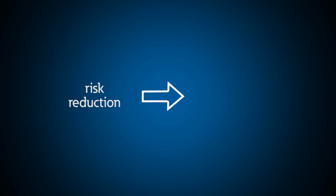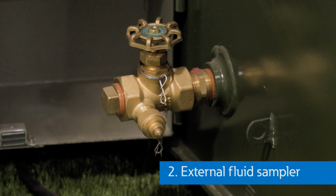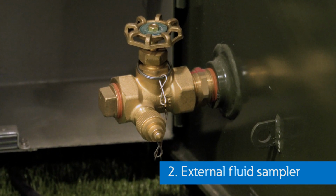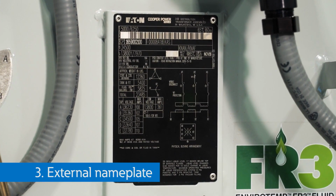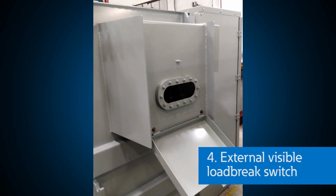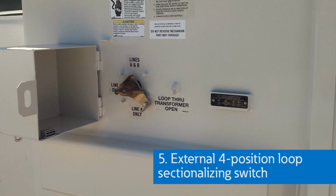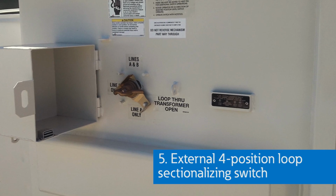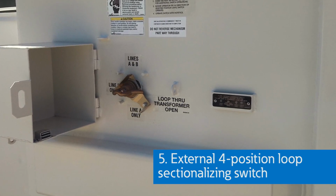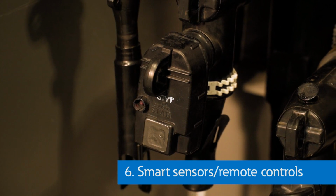Risk reduction involves reducing the likelihood of an arc flash event occurring. This would include incorporating features like, number 1, gauges mounted on the outside of the transformer, 2, external fluid sampling ports, 3, externally mounted nameplates that you can see without opening the enclosure, 4, externally accessible on-off or load break switch to ensure the transformer is de-energized before access, 5, a 4-position loop switch mounted externally for sectionalizing control, or 6, even adding smart sensors and controls so you can remotely monitor your transformer.